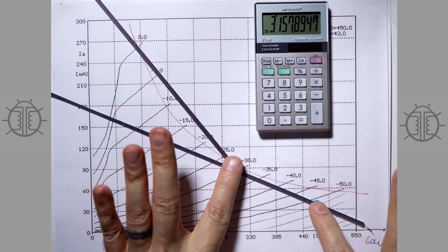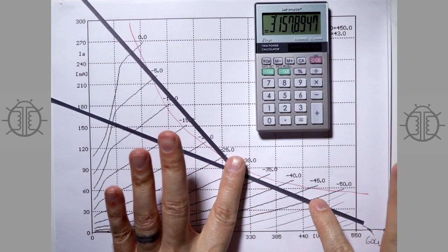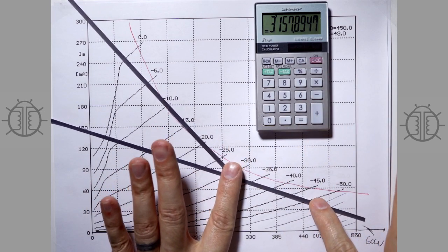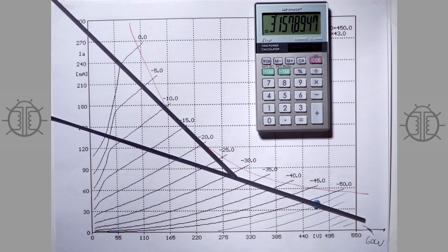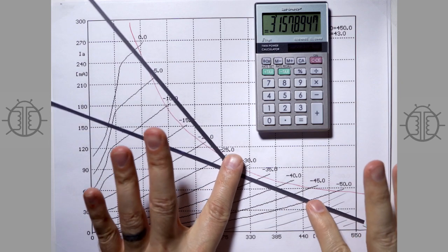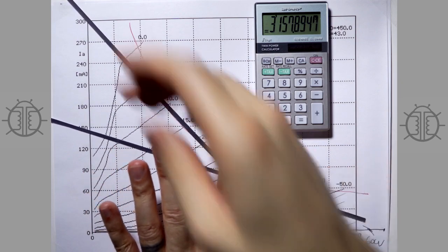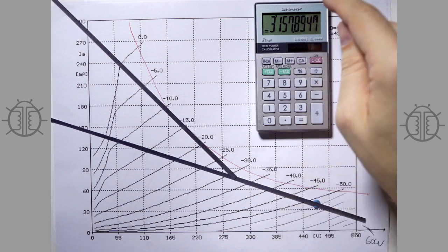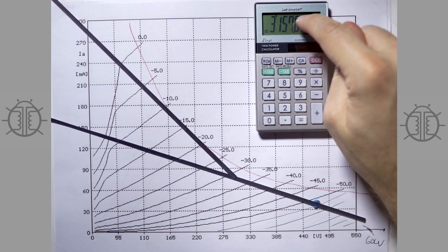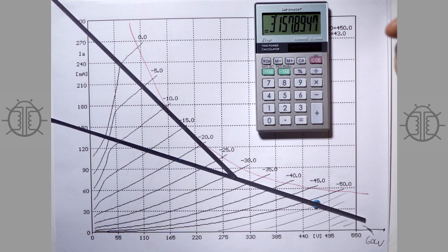You know, it might be better to keep it more within dissipation, so we could reduce our load or increase our load, which would kind of shift our load line down like this. Now remember, your speaker though is going to go over a wide range of frequencies. It's okay if it occasionally kind of does this, but you can see we've already ballparked our output transformer. You can see how easy it is to ballpark the output transformer primary impedance or ratio, because we know that 3K here, so that's going to be a 6K plate to plate. Each one's going to see 3K, and it's going to see 1.5K at the transition to class AB1. And so you can see how easy that was.